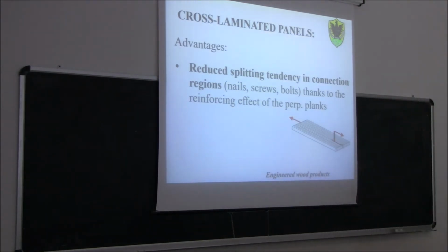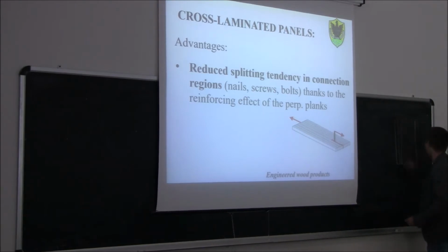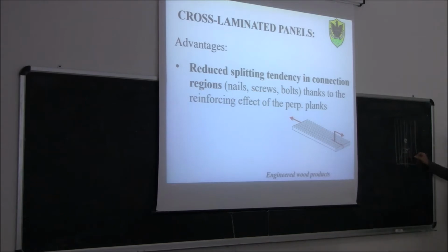We said that if we basically place a dowel on a timber, on a glue-lam beam, and then we pull, in general we will get some kind of secondary stresses. So the idea is that if this is, let's say, the glue-lam, we do a hole, and then we pull in this direction, we have a distribution of secondary stresses. If you do an elastic analysis of a plate like this, you will find that there are some secondary stresses in the tension direction that are going to act perpendicular to the grain.